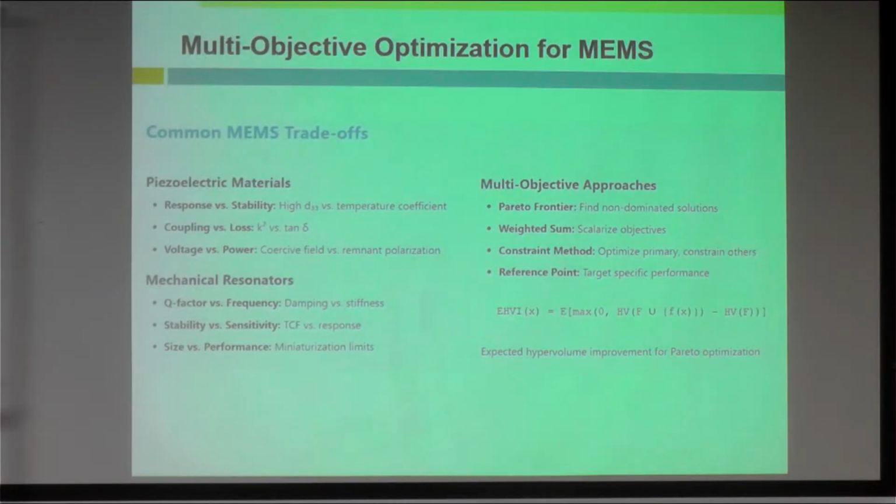Response means the material has a piezoelectric coefficient, let's say here in the case of d33, is it high versus the temperature coefficient? Temperature coefficient is whether it will expand with the change of temperature, or degrade. And coupling versus loss, voltage versus power, coercive field and remnant polarization of the material. This is in the case of a piezoelectric material.